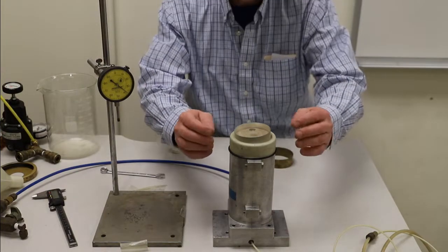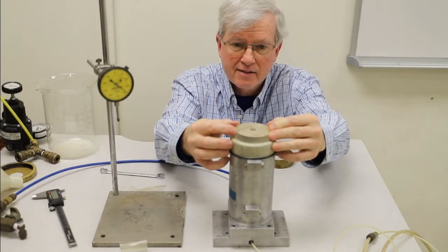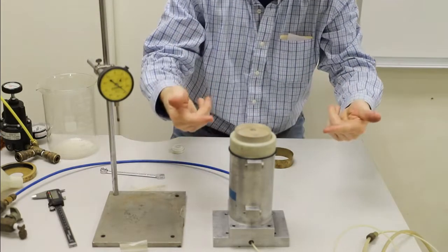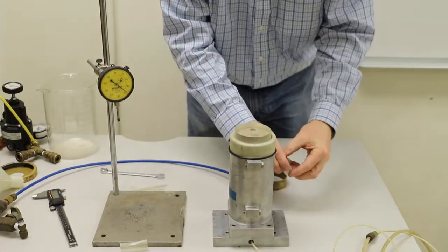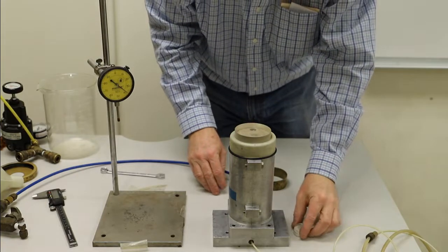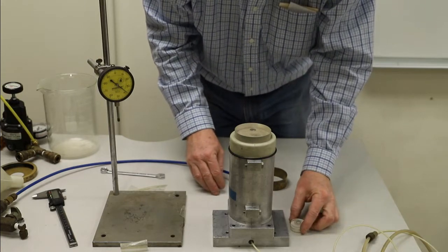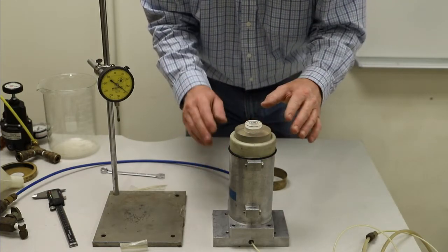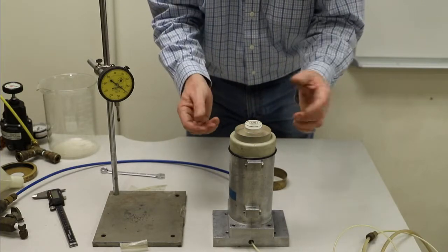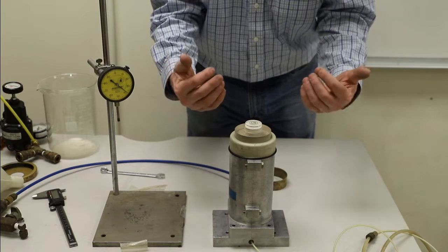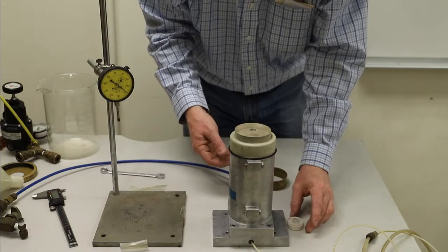Now we can see pretty clearly this is not level at this point, so how do we get a nice level specimen? We want to make sure the top platen and bottom platen are parallel, so that our cylinder is a right circular cylinder. And what we're going to do is take a bullseye level or a bubble level, and we're not interested in getting the top cap perfectly horizontal in the gravitational field, we want it to be equally unlevel as the bottom, or the table, or the floor that you're working on.